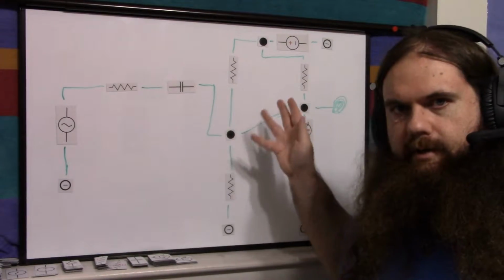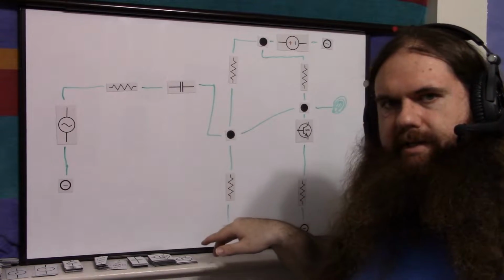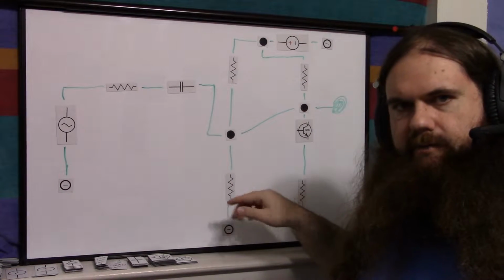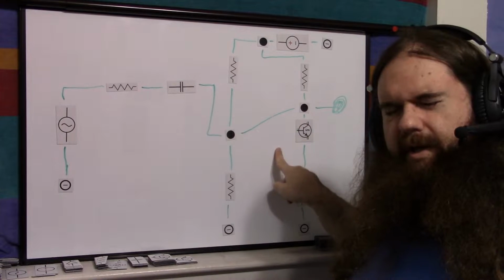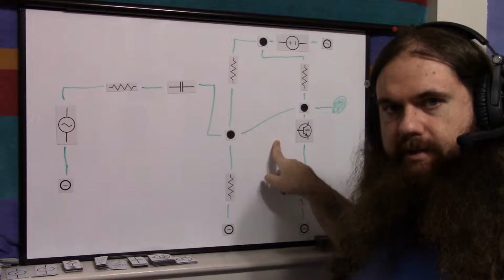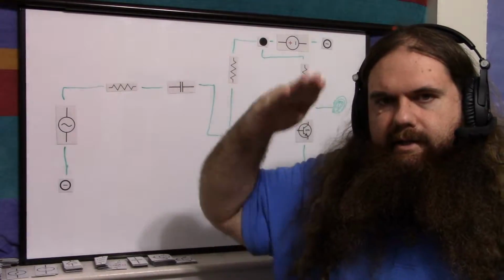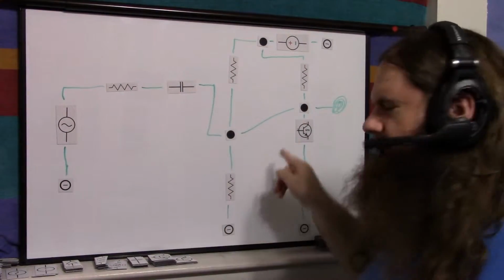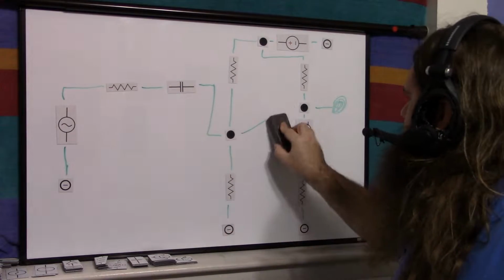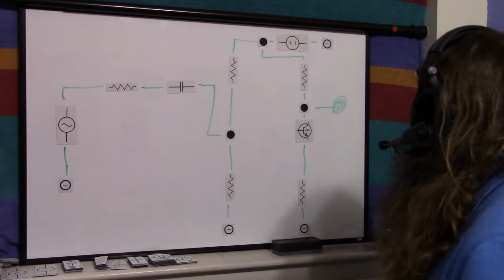And then you set up your currents and whatever to get the gain you want. But the point is, the bias with the emitter resistor moves the base voltage and the emitter voltage up so that the transistor is always on and it's in a range, so the base to emitter junction never turns off. Yes, I just realized I drew that line wrong, but you got the point.